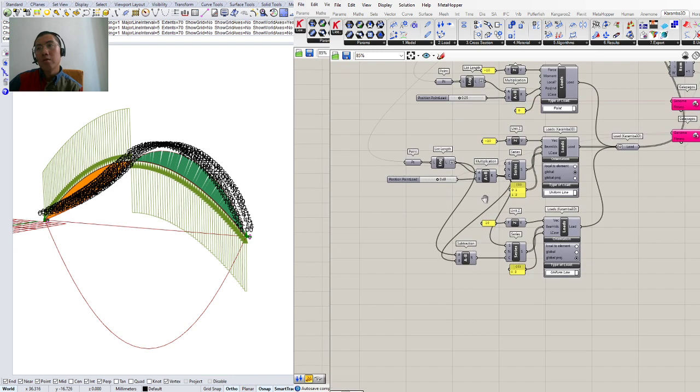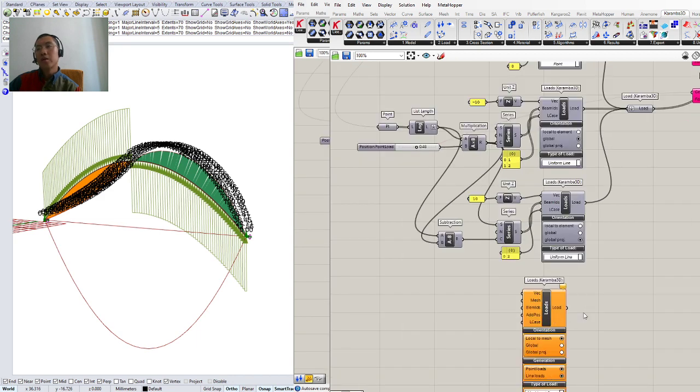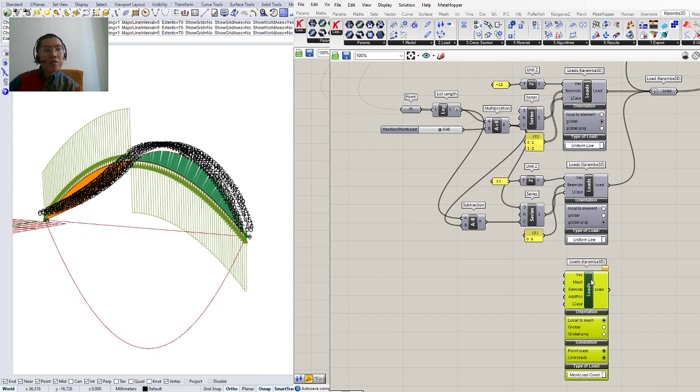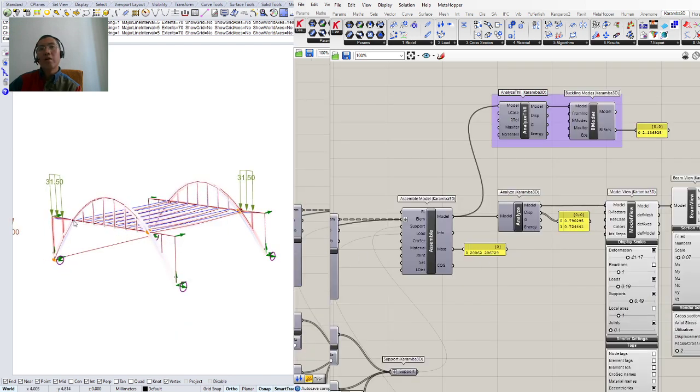We will be looking at surfaces, for example, in some future webinars, but you can define loads according to a mesh load. These meshes, or surfaces in a way, can be distributed according to beams with their element ID. So you can input a mesh, in this case maybe a floor plate. In our case for the bridge, we can say we have a mesh where we have the bridge, and then the load from this mesh is distributed on these horizontal members.